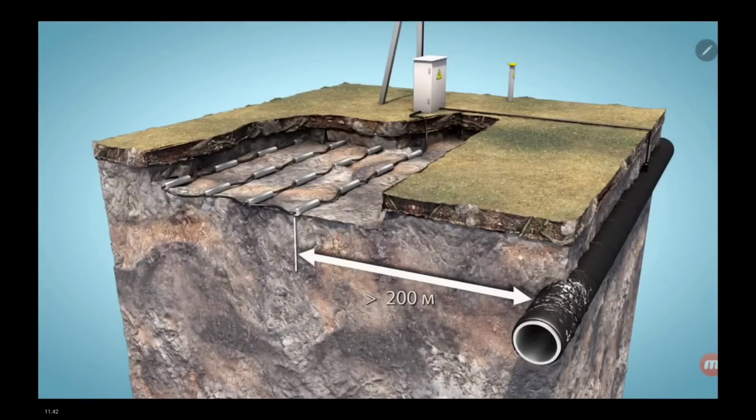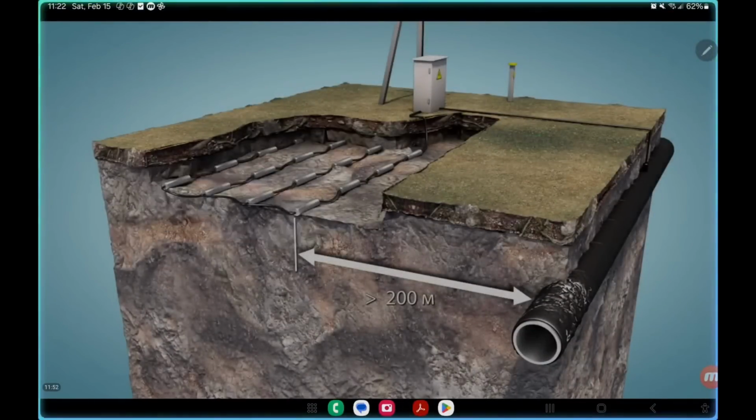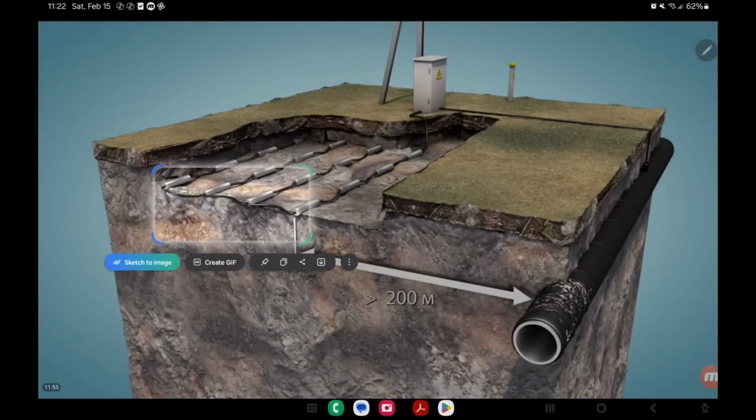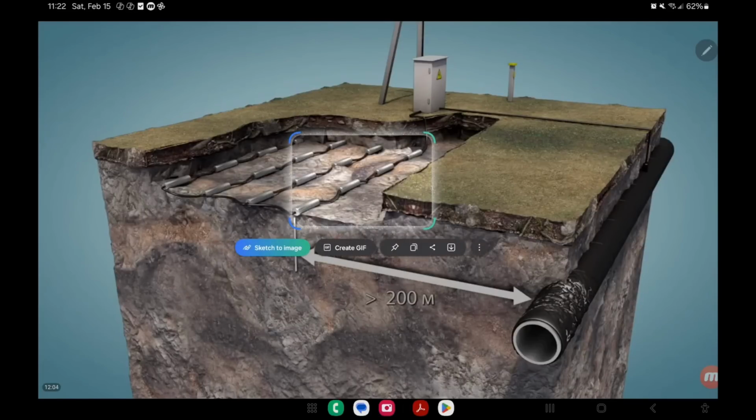They are also vertical, but notice that they are anodes connected to a common point. So we are talking about anodes in parallel, and each string or line of anodes in this case has 4 anodes for each parallel. So there are mathematical equations here, the Sunde and Darwin equations, and mathematical calculations are made to calculate the total resistance of the ground bed.